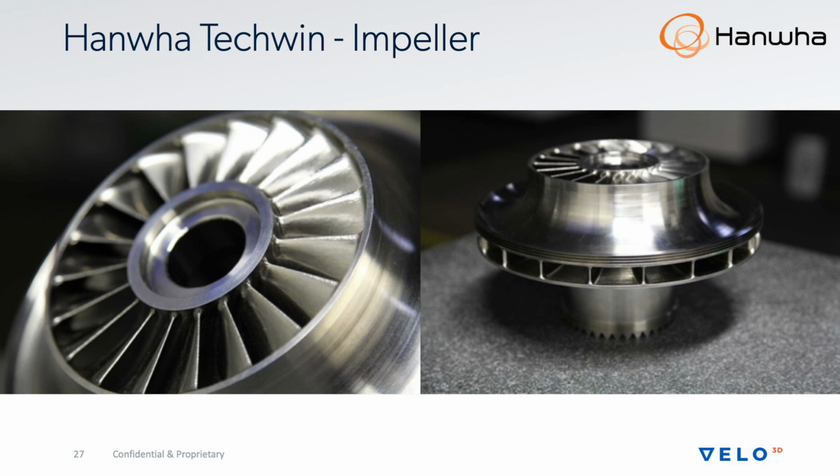And on other systems, a lot of these, again, think about everything below about 45 degrees or 40 degrees is going to have to be full of supports. The removal is very difficult. And then post-processing, to get those surfaces back to being acceptable, is much, much greater. And so it makes a much more difficult business case for this. So Hanwha settled on using the Velo 3D Sapphire system for this, and it came out with a great result.